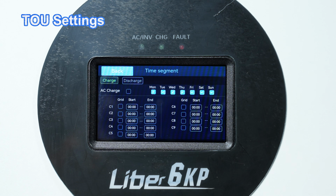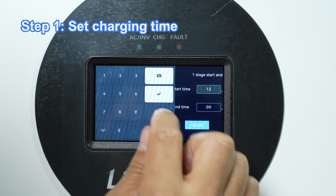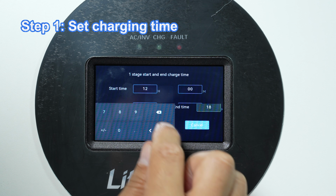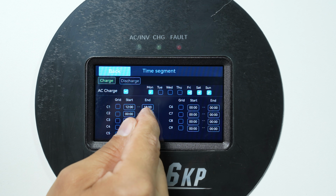Next is time segment, also known as TOU settings. This lets you schedule when the battery charges and discharges automatically. To set up charging schedule, first turn on AC charge, then choose the days you want the schedule to run and set the start and end times. If you need more than one charging period, you can add additional time slots.